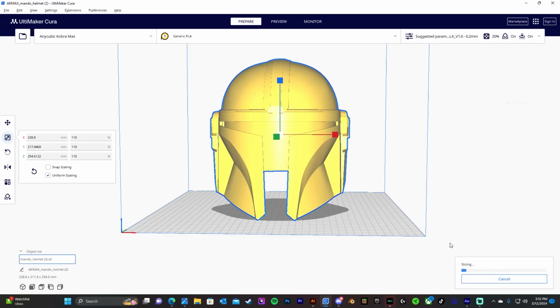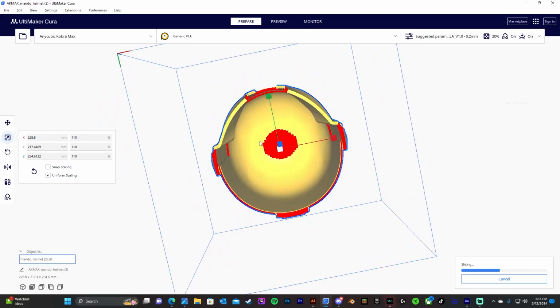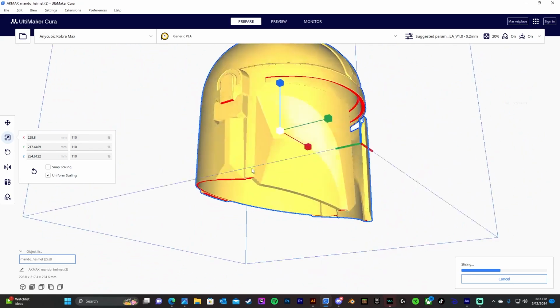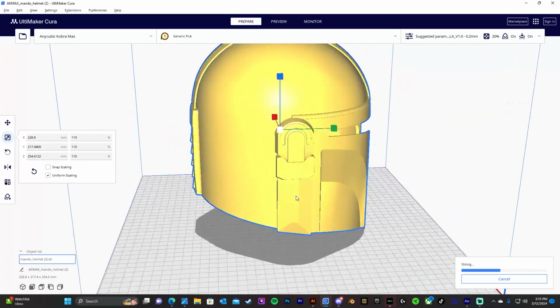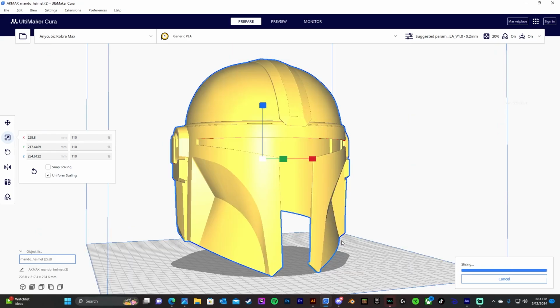It's not gonna take too long depending on the size of the file and the size of the print you're going to do, but that also depends on your computer itself. So following that, while we wait, this is where you can decide on your fine tuning. Now, like I said before, all of these red zones are considered overhang points that will need to be supported, because since this prints in layers, if the bottom layers are not supported, the top layers are going to fail. If the bottom layer fails, the top layer fails. Your print fails. That's very frustrating. Nobody wants to have a print fail. And right about there, we will be complete.